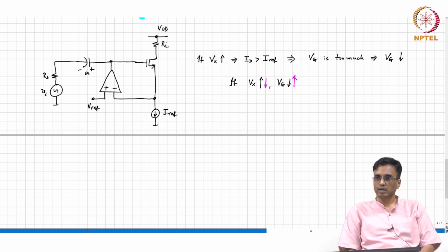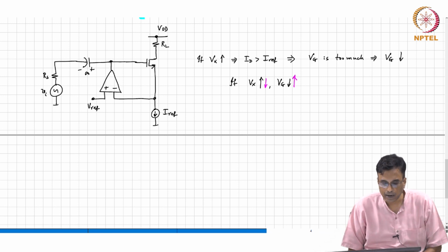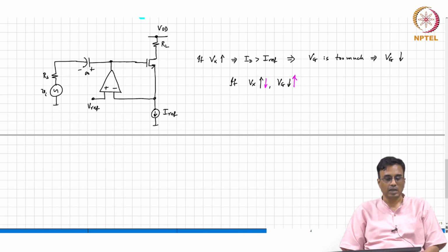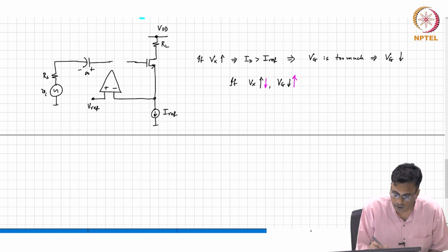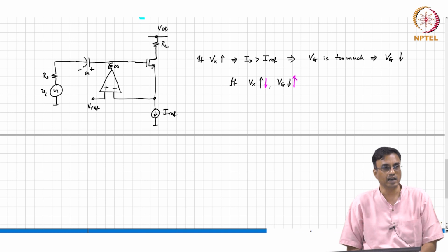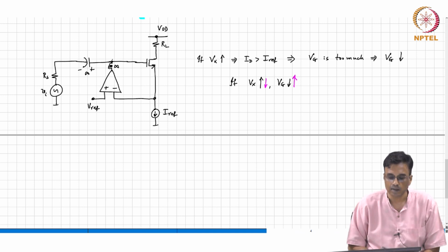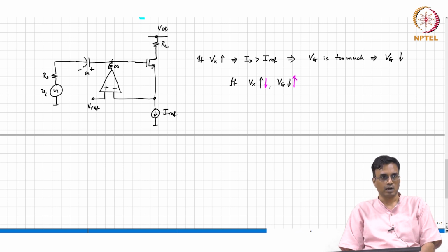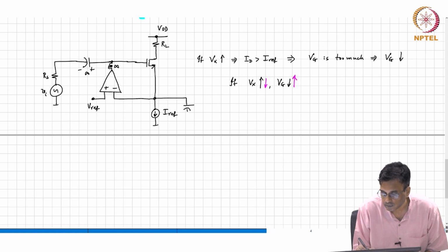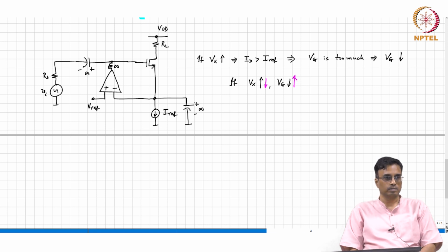Okay, fine. What else? Again we need to break the negative feedback loop. So, how will you break the negative feedback loop? Yeah. So, for example, you put an infinite inductor there, all right, and so that will break it. And what comment can we make? Are we done, or do we still need something else? The infinite capacitor at the source. So, the negative feedback loop only exists for DC bias. It is completely out of the picture for incremental signals, and this is our good old common source amplifier all over again.